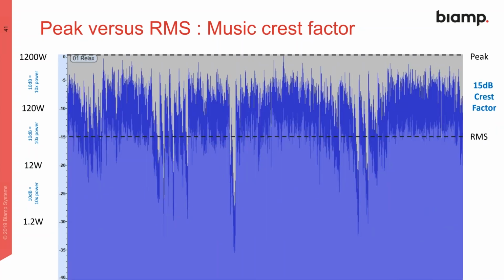And here's another one. This is another that comes in with about -15. And I might be a little bit low on this one. It was sort of the troughs. I kind of cheated the RMS down. It might be closer to -12 RMS. So you'd have a 12 dB crest factor. And so your required output power would be a bit higher.